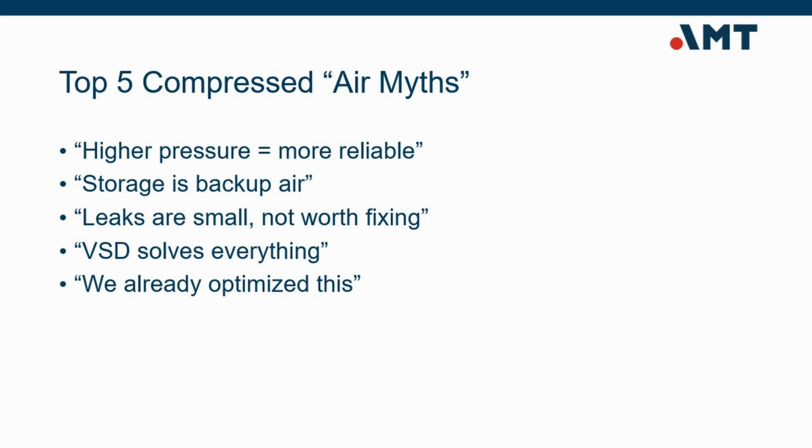Myth number 2: storage is backup air. Air receivers are often thought of as reserve supply, but storage is primarily for stabilizing demand fluctuations, not replacing compressor capacity. If storage is being used to compensate for undersized equipment or poor controls, the system design needs a review.